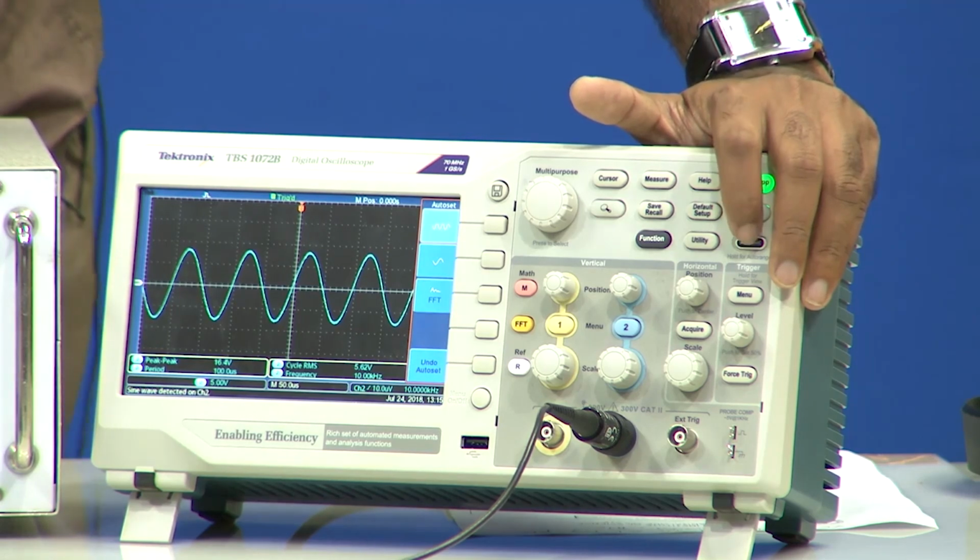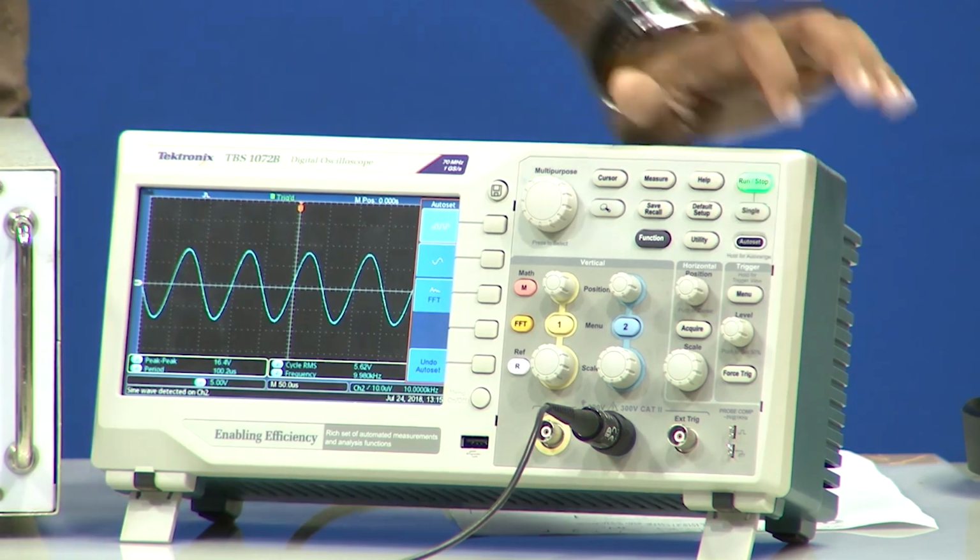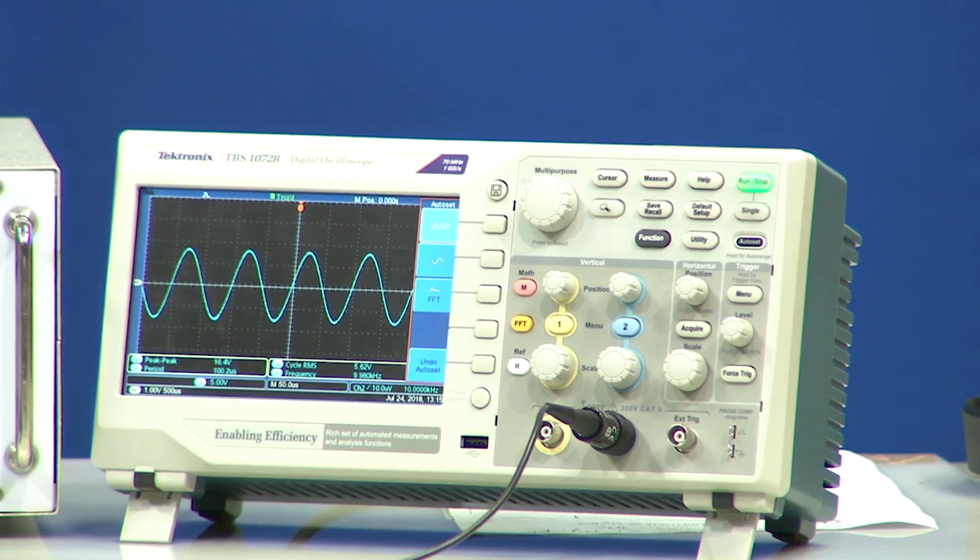Okay. So, we know that the saturation voltage of the op amp, when the supply voltage is 15 volt, is around 13 to 13.5 volt. So, that 13.5 volt will be the single side excursion. So, the positive side should be 13.5 volt, and the negative side should be 13.5 volt. When that voltage is reached, the output saturates, correct? So, with a gain of 2.2, let us first calculate the input voltage at which saturation will begin to occur.